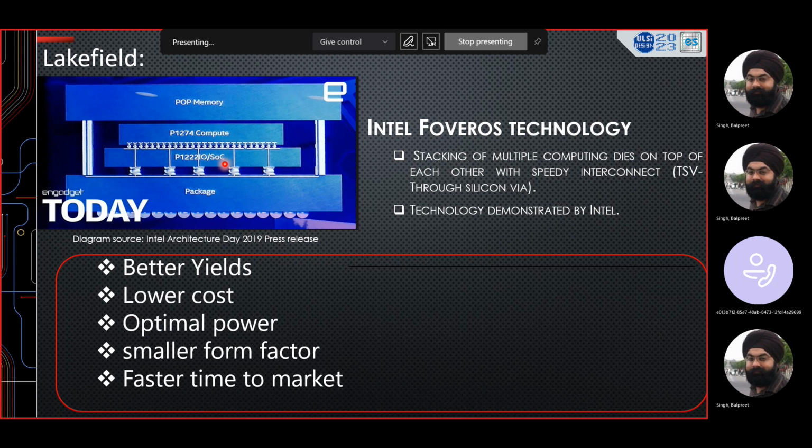Now, you can do the visual inspection for 5, 10, 20, 30, 50 pins. How do you really do that kind of validation for hundreds of pins? How do you really make sure that every transistor sitting on the base die, or the ground floor, and also on the first floor or the top floor, gets the required power supply within the tolerance limit of, let's say, 5 millivolt or 10 millivolt, whatever limit you keep in your design house? That's the unique challenge which you have not seen earlier.